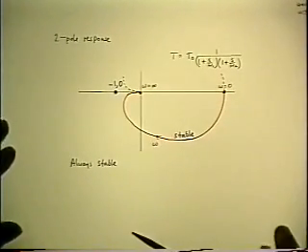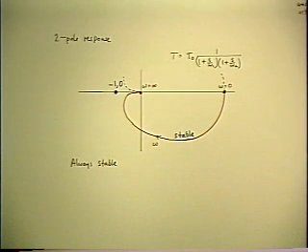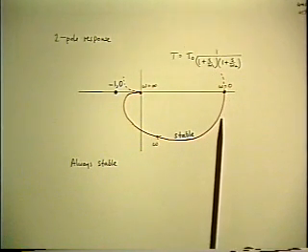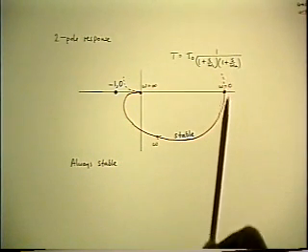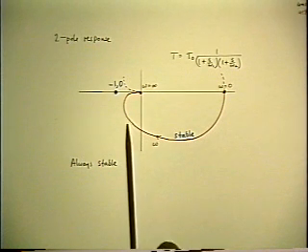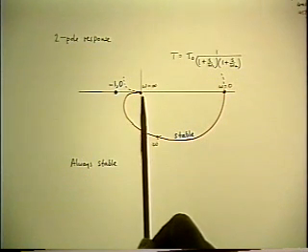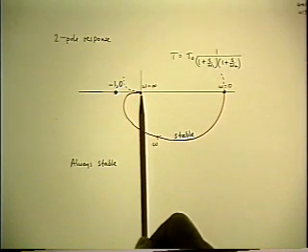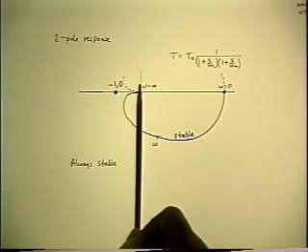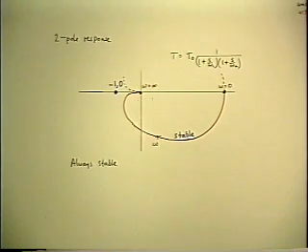So the next most interesting case is two poles. So you start out at zero frequency the same way on a semicircle, but then as you get close to the second pole, the magnitude will go down faster and the phase angle will increase faster, and you'll eventually go to an infinite frequency at zero magnitude with a phase angle of 180 degrees. And then you have the vertical inversion of that also that closes the contour, and you look at it and you say, does it go around -1? And the answer again is, no it doesn't, and it never will.